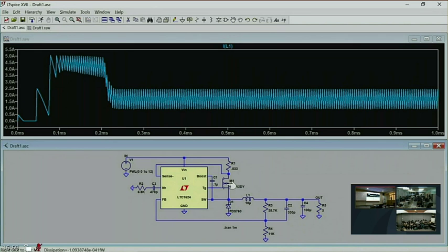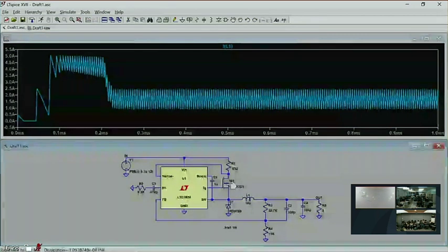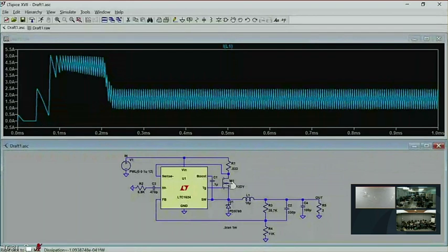All right, now this thing, to regulate the output voltage, the output is sensed with a resistive divider. And a divided version of the output is compared to a reference voltage. The difference between the divided version of the output and the reference voltage, that is the error voltage, and the error voltage is amplified by an error amplifier. Now, for error amplifiers, I'm only going to use transconductance amps for error amplifiers. I won't use an op amp, but a transconductance amp. A transconductance amplifier amplifies an error voltage to a current.